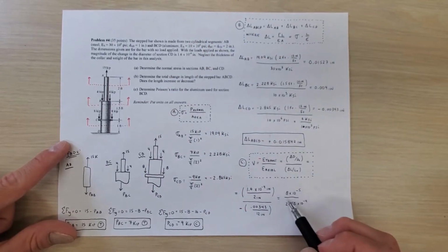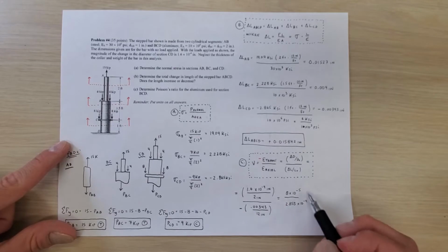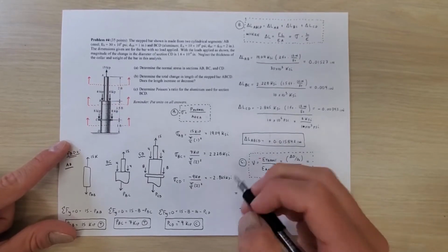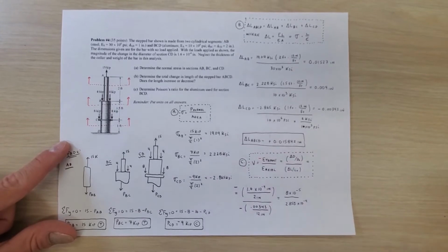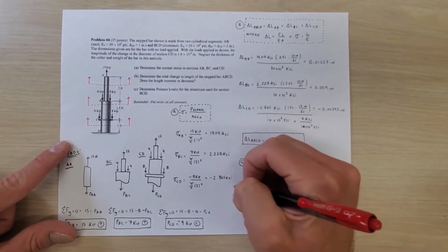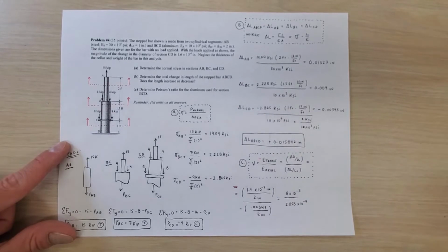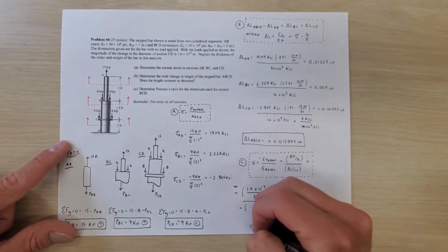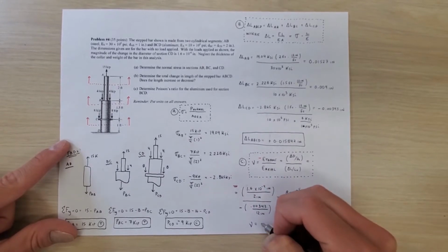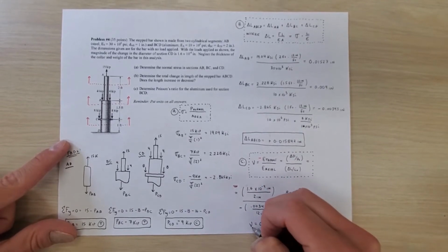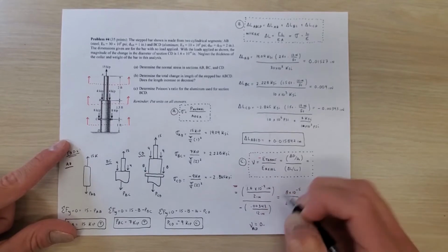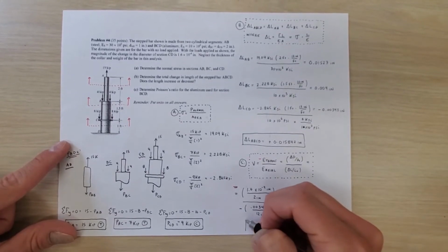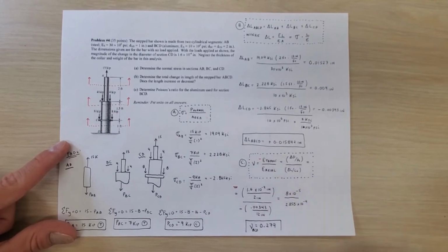So when we do all that, what we get down here is we're actually going to get a positive value for Poisson's ratio, right? Because the whole thing was negative, and I guess that's why I wrote this in red, so we can draw this negative as kind of the negative of the whole problem. And we've got a negative on the bottom, so those negatives cancel out, and we get the Poisson's ratio for segment CD, which is really BCD, is going to be equal to 0.279. And there are no units, so we're good to go.